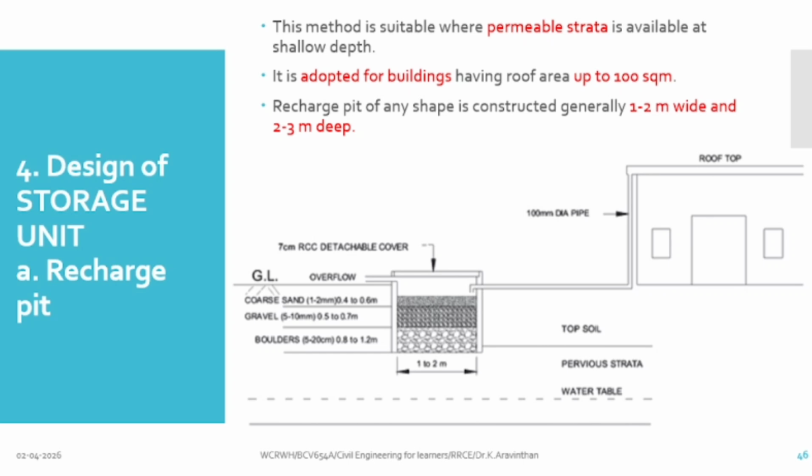What do you mean by recharge pit? It is again nothing but a layer of 3 materials. Boulders. Boulders means large size stones. When you are laying a road, you might see boulders. They will lay large stones at the bottom, which are called boulders. The next thing is gravel. Above that you have sand. This size they will be having. The water will be sent here.